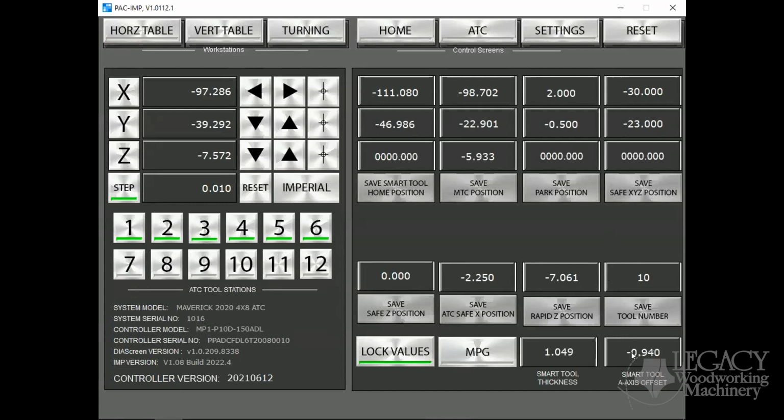Okay, and it will be set to something, but if you measure and the diameter of the part is larger, and I'm going to use round numbers, let's say it's 1/10 of an inch, 0.1 inches larger. So you're trying to get 1.5 and you're measuring 1.6. Then you would have to increase this number by half that difference. So you'd have to increase it by 0.05. Now, if you measured it instead of 1.5, it was measuring 1.4. Again, I'm using very large rounded numbers. That means it's 1/10 of an inch smaller. So this number would have to get smaller by 50 thousandths, 0.05.